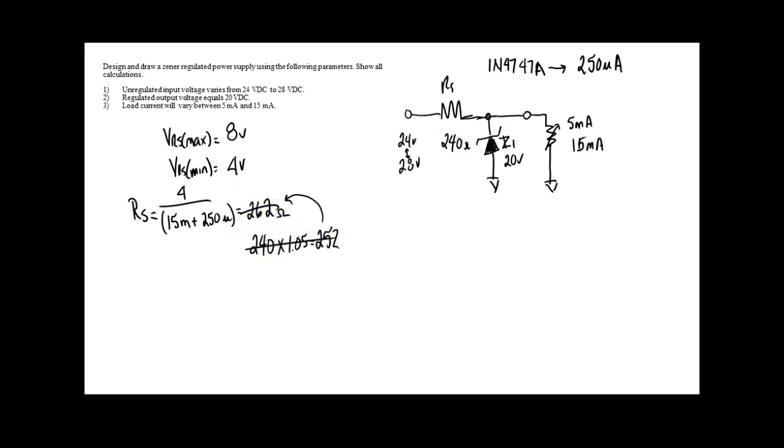Now we're through with this calculated. We're through with that. Y'all understand that? We're through. This is everything else we're going to calculate with the resistor we chose. So this is the resistor we chose. We know two things about our resistor. We know the value and we know the tolerance because we chose a tolerance. So now we've got to choose the wattage rating on the resistor, right? Okay.